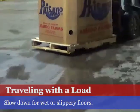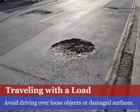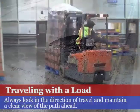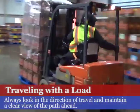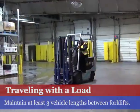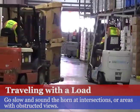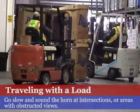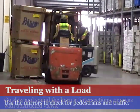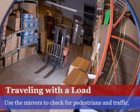Slow down for wet or slippery floors. Avoid driving over loose objects or damaged surfaces. Always look in the direction of travel, and maintain a clear view of the path ahead. Keep a distance of at least 3 truck lengths from the vehicle ahead. Slow down and sound the horn at aisle intersections, or other locations with obstructed views. Use the mirrors to check for pedestrians and traffic.